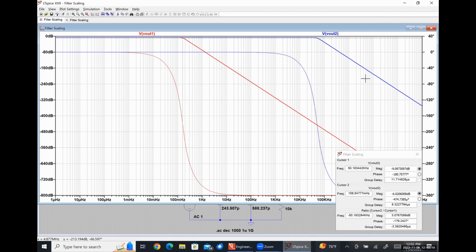Yes, sir, Gabriel. So for this particular circuit, all I put in was just a 1 volt AC source so that my output voltage is my frequency response, because whatever V out is divided by 1 volt over all frequencies is just giving me my transfer function. I'm not looking in particular here for the voltage drop across any of the capacitors, although we could look at those and see what kind of weird things we're going to get.